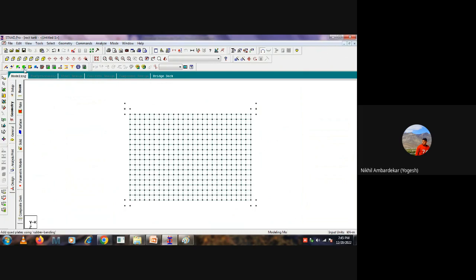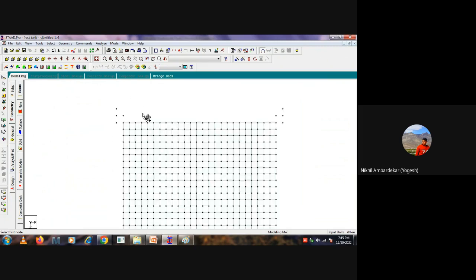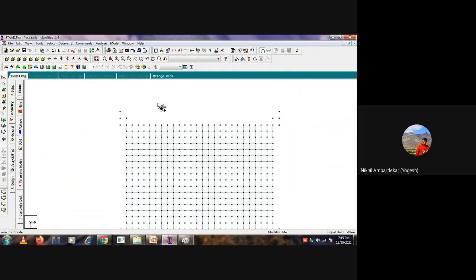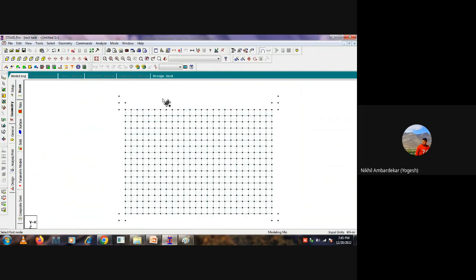Now for the base slab it's fine, you can draw as per your convenience. Orientation is not that important because we are applying the loading for the base slab, which will be universally minus or plus, parallel to y. So we can just create these 4 plates here.